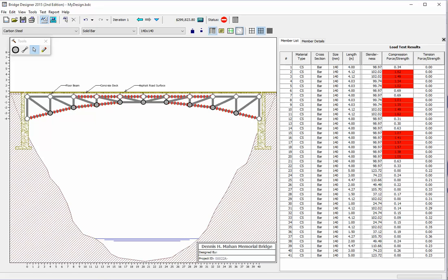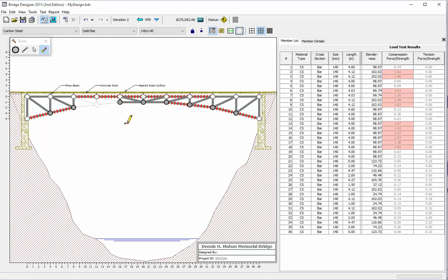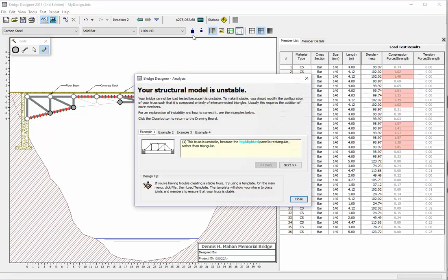You got a message saying your model is structurally unstable. Alright, that's wonderful that you brought that up. If your bridge is just gonna immediately collapse and burn, like if it's not even possible to consider being built, that's what it'll tell you. It'll tell you your bridge is structurally unstable. It'll give you a pop-up with, actually let me see if I can show you. Let's delete a couple members here and then try to run the simulation. Alright, here we go.